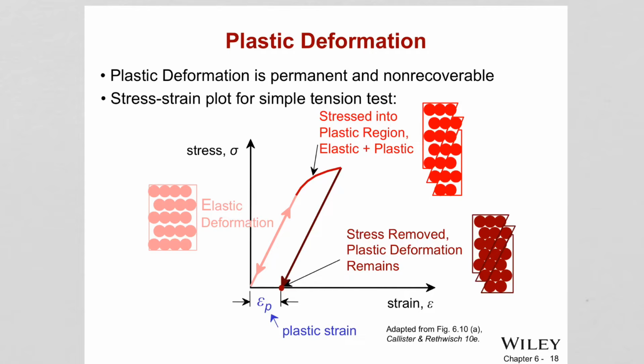This again summarizes the stress strain curve, okay? So the machine records the force and change in length and converts them to stress using the equations we learned, and strain, and then gives us the stress strain curve. It measures the force that needs to be applied to keep the deformation rate constant, and then gives us the stress strain curve.